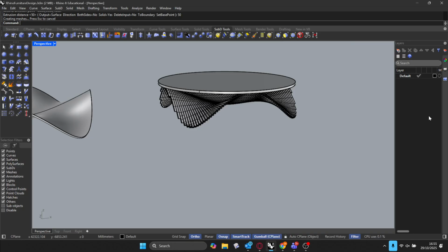Nice, thank you. And what was the wireframe part? Extract wireframe was from the curve menu. Go to curve, then curve from objects, and do extract wireframe. Just select whatever objects you want to extract the wireframe from. This one, yeah. Enter and just drag it across.